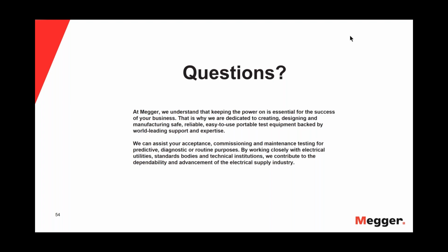And of course, the coincidence method relies on the acoustic energy from the flashover in combination with the electromagnetic pulse. So if we've done a breakdown test, we kind of know how much voltage we have to use. And Henning talked about this also, but with a multi-stage thumper with multiple capacitors, you can thump at a very high voltage, but many times you don't need to.